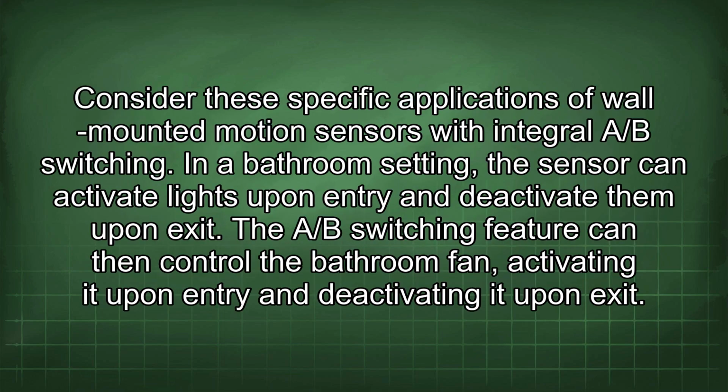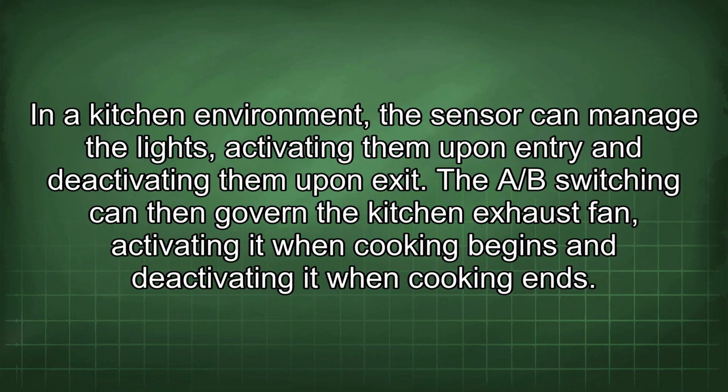Consider these specific applications of wall-mounted motion sensors with integral A/B switching. In a bathroom setting, the sensor can activate lights upon entry and deactivate them upon exit. The A/B switching feature can then control the bathroom fan, activating it upon entry and deactivating it upon exit. In a kitchen environment, the sensor can manage the lights, activating them upon entry and deactivating them upon exit. The A/B switching can then govern the kitchen exhaust fan, activating it when cooking begins and deactivating it when cooking